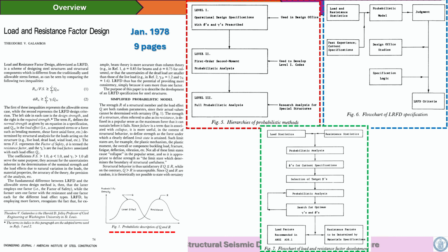That's another important challenge for the next generation code: how you combine, for example, earthquakes with wind, with flood, with other natural and also technological hazards, whichever is called NATECH. And you can only do that by considering an approach based on probabilistic analysis. And this is the way these types of approaches are implemented these days in codes of practice.